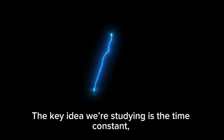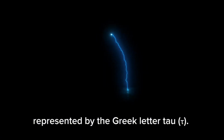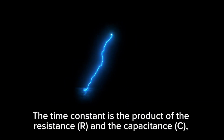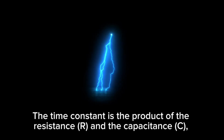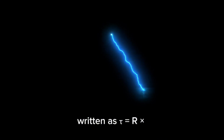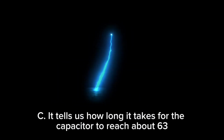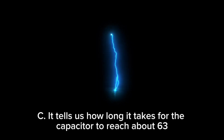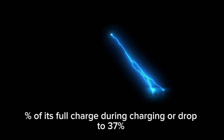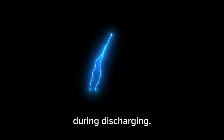The key idea we're studying is the time constant, represented by the Greek letter tau. The time constant is the product of the resistance R and the capacitance C, written as tau equals R times C. It tells us how long it takes for the capacitor to reach about 63% of its full charge during charging or drop to 37% during discharging.